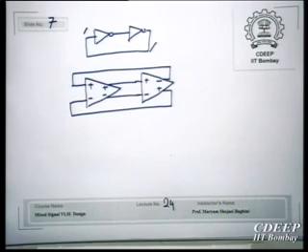I would not call it efficiency, because then we have more number of components. But with two stages, we can get a very fast ring oscillator, even answering your question. Here, it's possible to get 3 to 4 gigahertz VCOs just in CMOS.